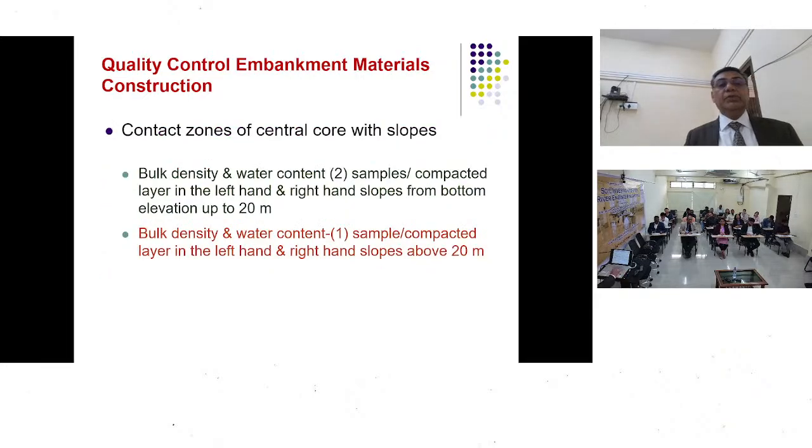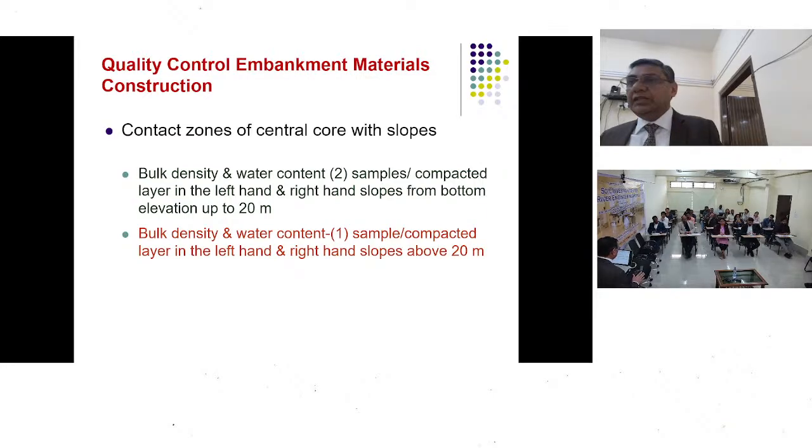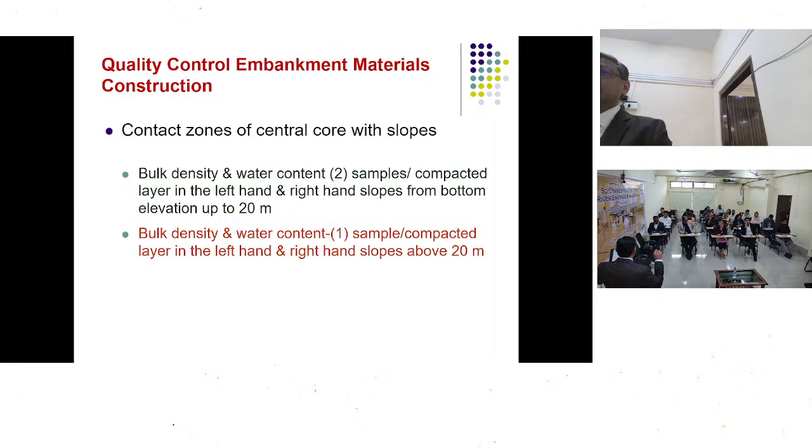In one project we had visited, I'm sharing what happens. We visited the project, and their instrumentation was being carried out. And what do we do in instrumentation? The instruments are placed in the clay core, the shell and the filters, and finally the cables have to be taken to a center where you are going to have the data collection center. They had dug below the FRL in the clay core to take the instrumentation cable, and when we asked them how they were going to fill it back,